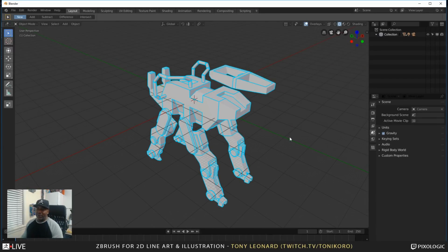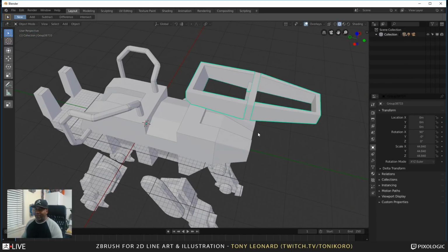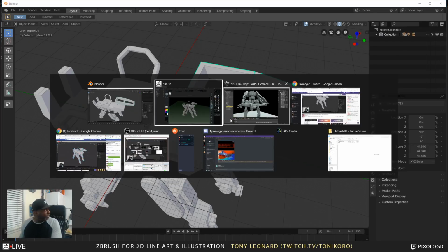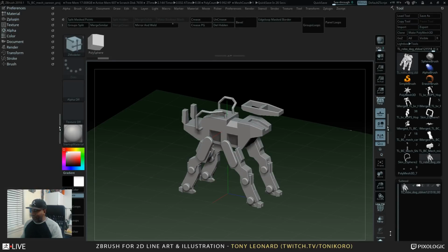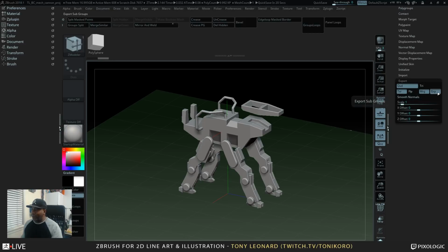So now pretty much what I can do is take each piece and start to work on it, each little sectional piece in detail. One of the things that I need to do here really quick, I need to go back to ZBrush. I actually forgot when I exported it. I need to look at the export settings, and probably turn off merge UV coords, and I think texture I don't need, and maybe even group.